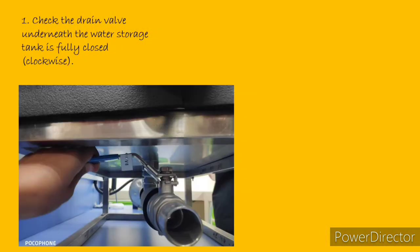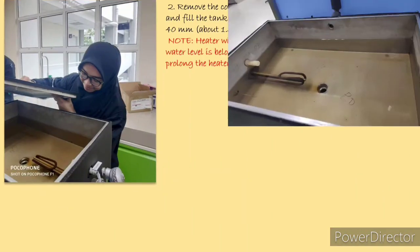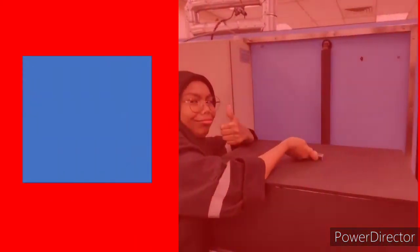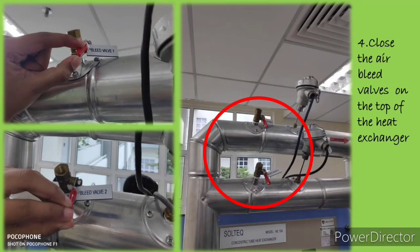First, check the drain valve underneath the water storage tank is fully closed. Next, remove the cover from the storage tank and then fill the tank with the water within 40 mm. Replace the cover on the storage tank and then close the air bleed valve on the top of heat exchanger.